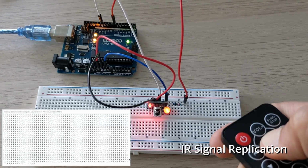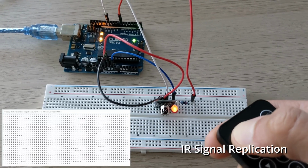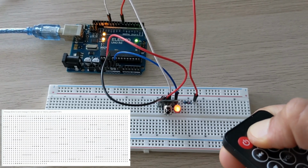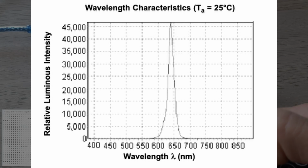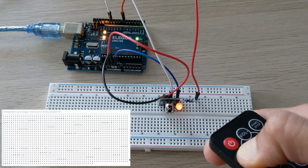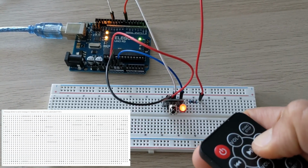Here I tried to punch in custom light pulses through a red LED emitter that could be interpreted as valid signals by the infrared receiver. But this would never work, since this LED peaks at about 640 nanometers wavelength, which makes sense because it's meant to output visible light, whereas we would need a 900 to 1000 nanometer wavelength for an infrared receiver to pick up that signal. There are more details on the blog post about this.